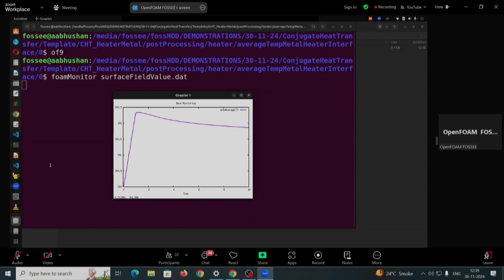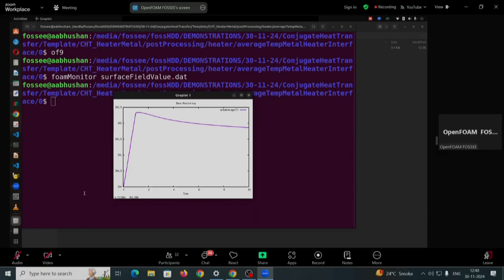Whenever you are doing a transient simulation, it is very important for you to sit down. This also came out in yesterday's talk, and it is very important. Whenever we take courses over here, we tell the students: before you touch the simulation, sit with a pen and paper and write down what you need and what you're expecting. What are the results? Any theoretical analysis that needs to be done, is done. That is the first step of CFD. The first step of CFD is not meshing. The first step of CFD is to take a pen and paper and completely break down your problem on the paper itself.